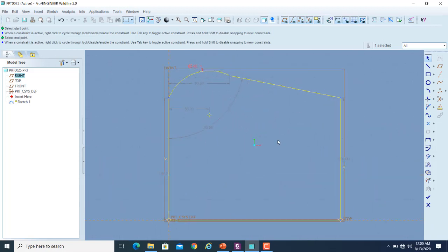So it will change to the active dimension. So now these are the weak dimensions which are dull in color. And once you come out of the sketch command, automatically those dimensions will become permanent. Otherwise you can use your own dimension manually also. So if you look into these tabs, the dimension tab is also available over here, and if you click on that arrowhead, these are different modes of dimensions that you can use.